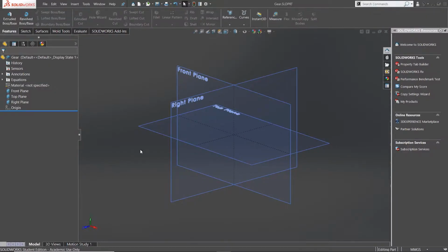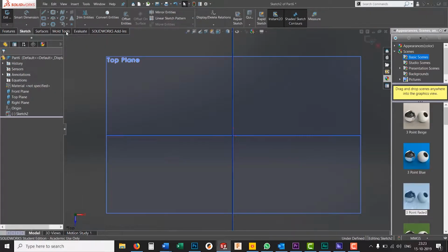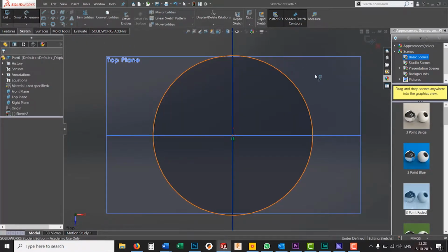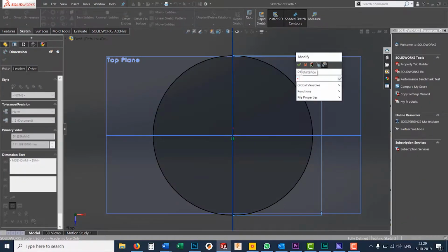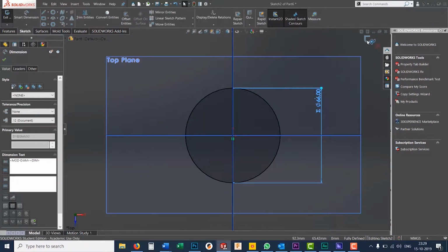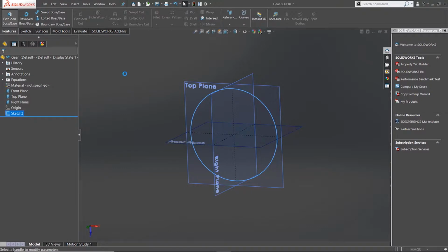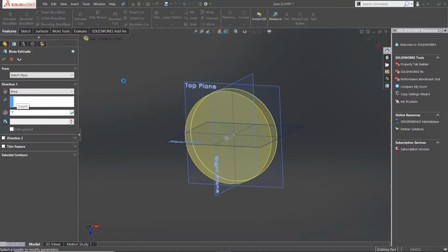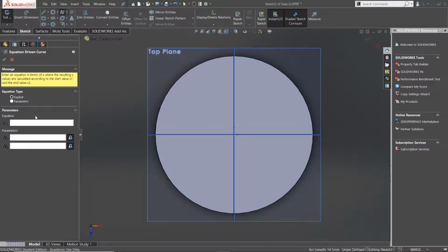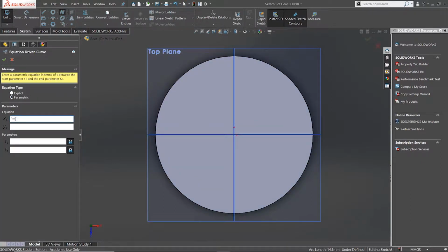We're starting with drawing a base cylinder with the outer diameter. When you use variables, don't forget to place them in quotation marks. Then the cut extrude. This starts with the most important shape, the involute. Engineers struggled for a long time to find out that this is the optimal shape for straight gears.